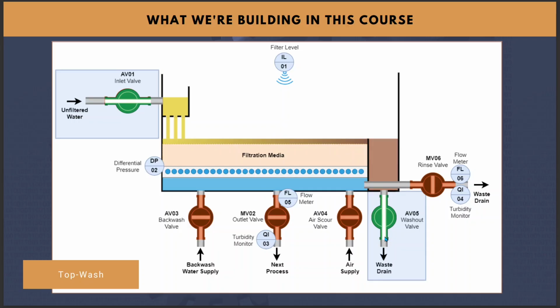So what we should be left with at the end of this stage is filtration media backwashed and cleaned, and any residue left on top of the filtration media replaced with unfiltered water that would be safe to pass back through the filtration media. If this step wasn't done, we'd end up with dirty water that's just come out of the filtration media being put straight back onto the media, so we'd have an ineffective clean.